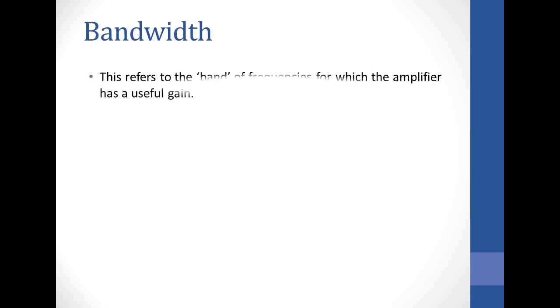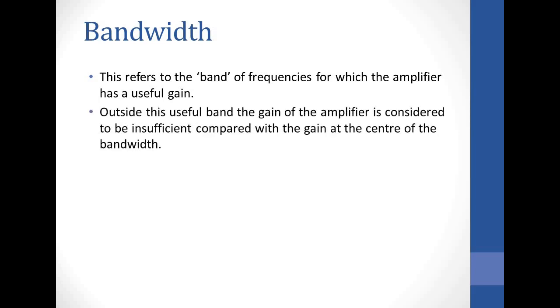So bandwidth, we also looked at bandwidth, which is the range of frequencies being amplified by this amplifier. So if you are asked what is bandwidth in respect to amplifiers, it is basically the band of frequencies which an amplifier can amplify. We can also mention that any frequencies outside that band will not be amplified. For example, 100 kilohertz cannot be amplified using the audio frequency amplifier.